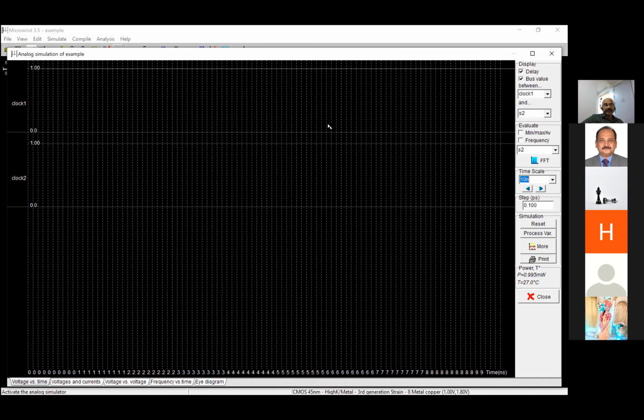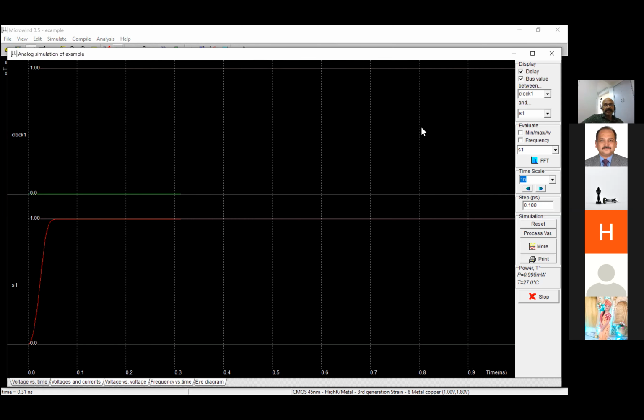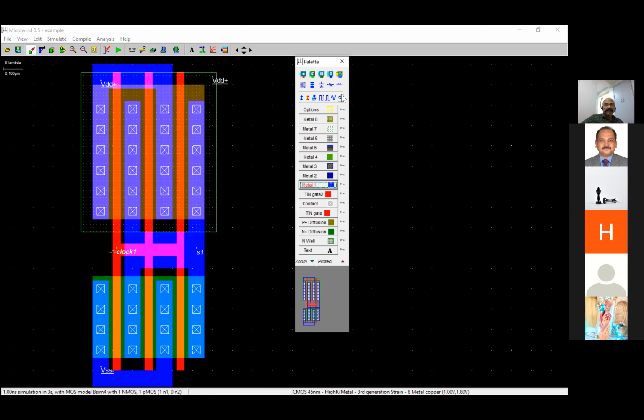Sir, last step. Sorry? You lost something on the last? Yes, sir, the last one. Yeah, so on the palette you see a visible node, an eye-like symbol. It looks like a visible eye. Yes, open eye. So left click on this one and left click on the node where you want to apply it. I mean, you want to observe the node. So any node you wish to see in simulation, you have to apply a visible node to it. Yes, sir, done. Now you can click simulation.